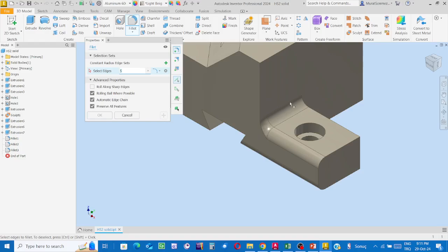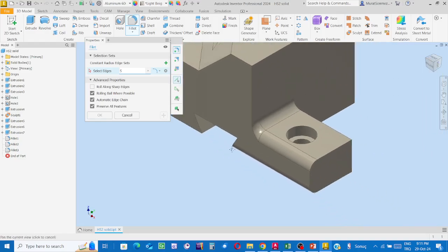Although it is so, why is it strongly recommended that the edges are to be rounded? Well, the reason comes from the strength of materials. If an interior edge is a sharp edge, whenever the object is loaded by external forces, then along the sharp edge the atomic bonding forces within the body will tend to take infinitely large values. Since it is impossible, the result will be a failure, the object will be broken.